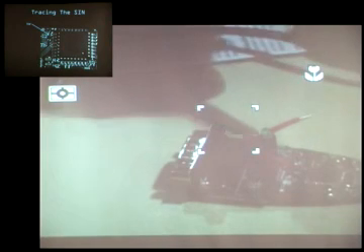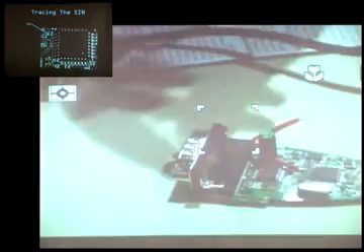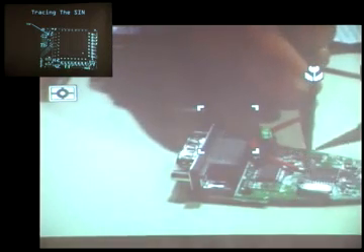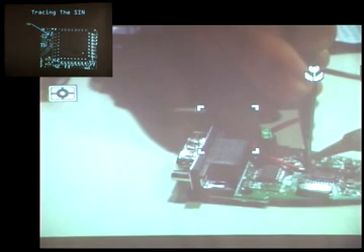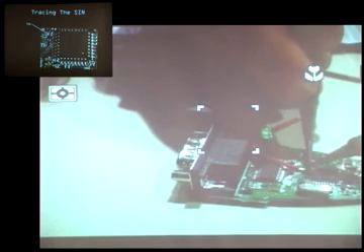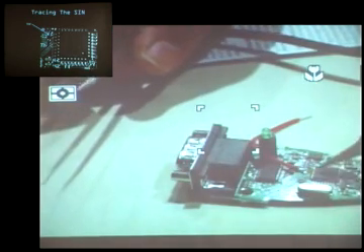Light it up, take my soldering iron, and the first thing I'm going to do is use flux. Now, the interesting thing is that it's very cold in this room, so the flux is a little bit gooey. It's not going to flow, so I actually put a little bit on my tweezer here. I'm going to warm it up with the soldering iron, just hold it close to it. And what will happen is the flux will start running and sort of just coat everything with a nice gooey layer. There we go. So now I've got a little bead of flux hanging out right over there.